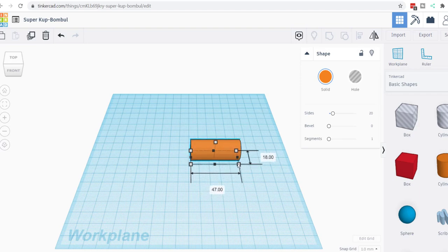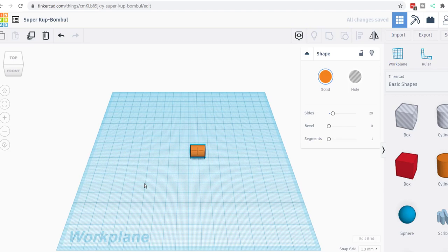You can grab one of these squares and drag that out however you want. I like to plug in my dimensions. This one here is the diameter, which was 11 millimeters, and then we had the length, which was 14. And then we have one more dimension we have to put in. You'll notice that our tank is 20 millimeters tall. Well, we don't want that. We want it to be 11. And now we have our tank set.